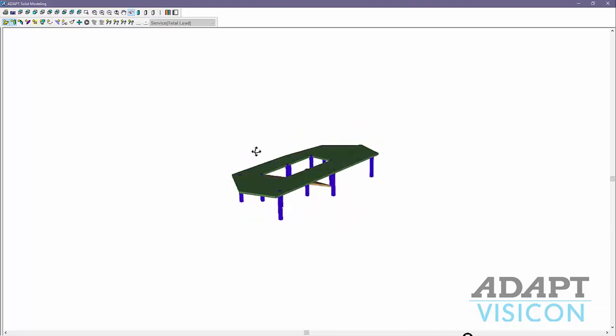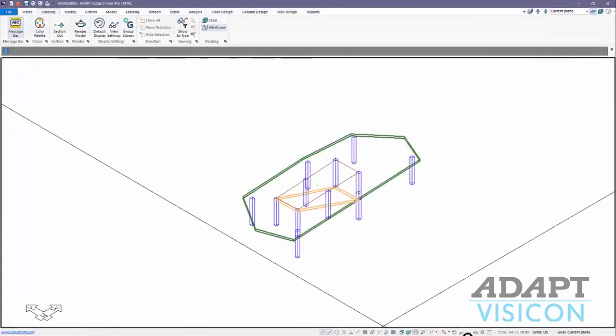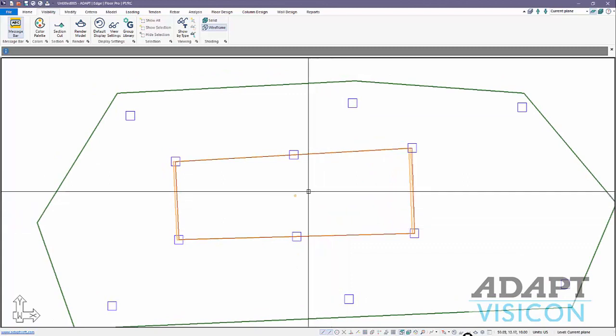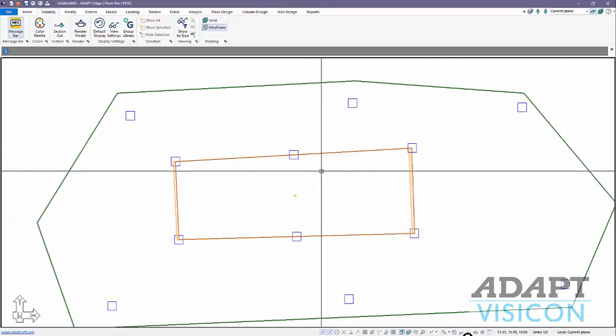It may be required for continuity of a lateral system that's a moment frame versus using workarounds. It might be more applicable to earlier versions of the software. So we've modeled this ramp. A couple of other things to note is any beam connected to the ramp or column can be offset downward and connect automatically to the ramp.